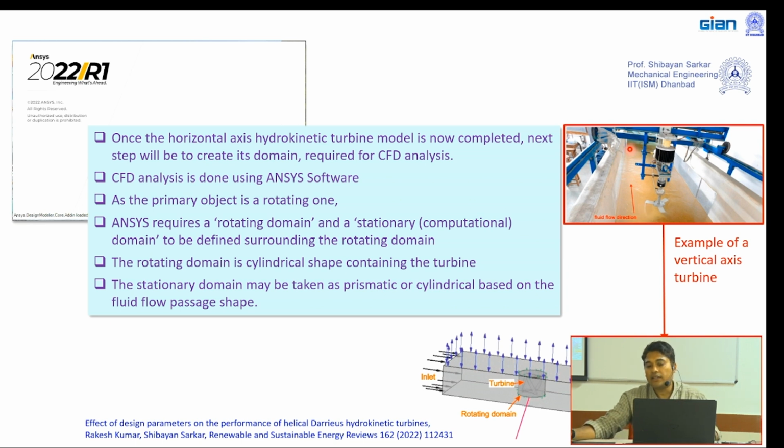And in the rest of the part, the fluid is already coming in through the channel and going out of the channel. So this is another zone where normal fluid is entering and going out. Surrounding this rotor and inside this rotor there is also fluid, but the influence zone will be cylindrical. Here the solid object itself is the rotor. So three things we have got. One is the solid object, the rotor. Another is the influence zone when the rotor is rotating, which will be cylindrical in shape for this particular case as well as for our case.